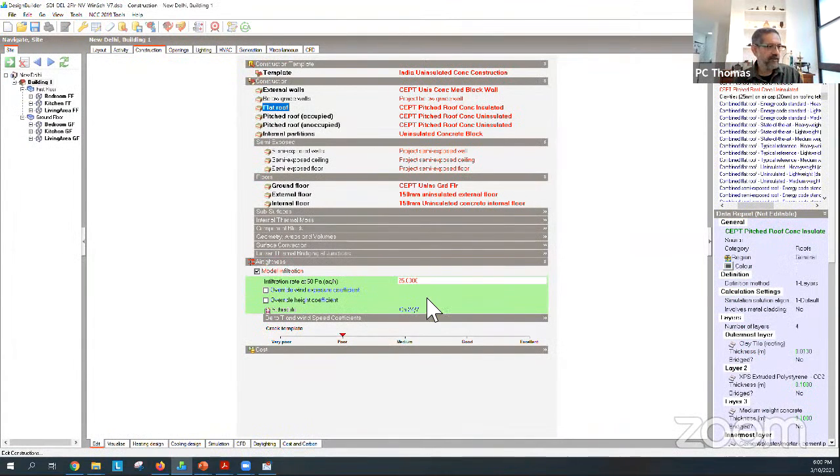So now you can say, okay, I did a blower door test and my house only leaks at 10 air changes per hour at 50 pascals. You can put that number in, okay? So if you have test data or you have some research on test data, do that. If you don't have any, leave it at 1 air change per hour or the default, which is 25 air changes per hour at 50 pascals, okay? Hopefully I've answered that question. The other part of your question, I thought I've already answered, which is all those layers and how to calculate U values and so on.